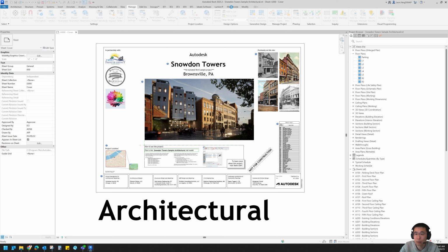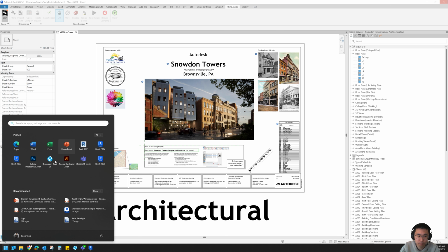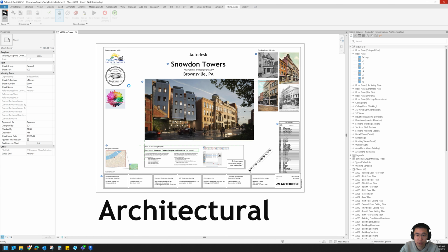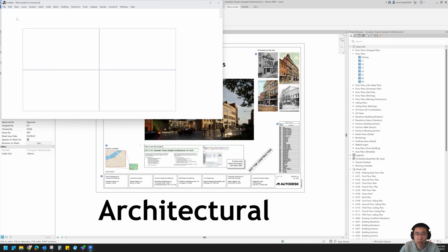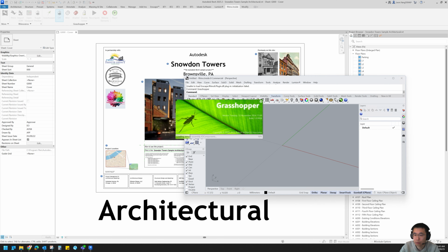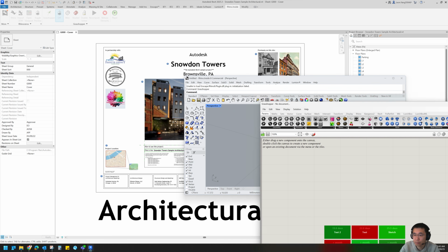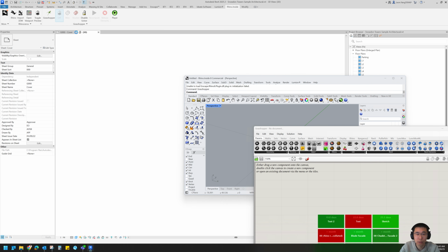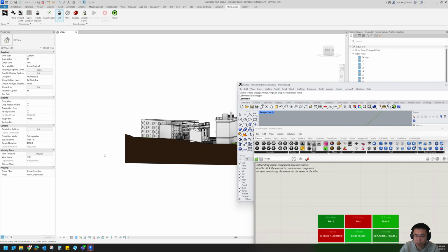And then the next step is to start Rhino from Revit, because if you open Rhino from your normal location, then you wouldn't see the Rhino.Inside plugin in Grasshopper. Now it's opened, and we turn on the interface of Rhino. Then we type in Grasshopper to start Grasshopper, and then we're all set. We're going to the 3D view because it's easier to understand what's happening.